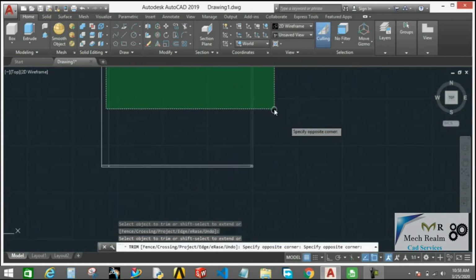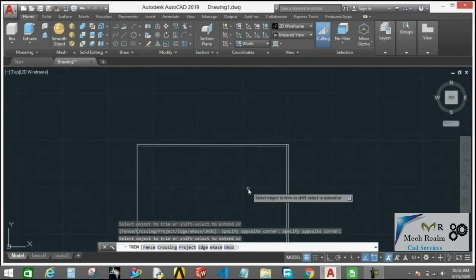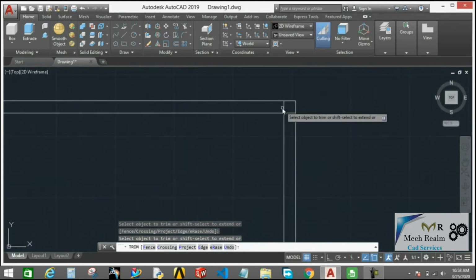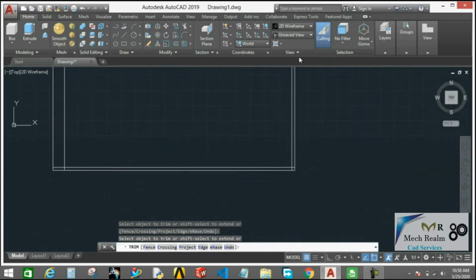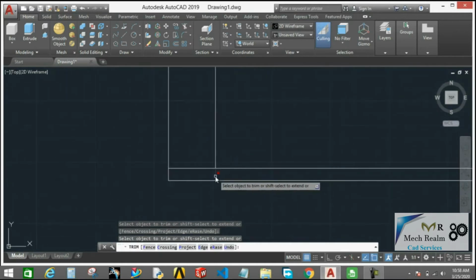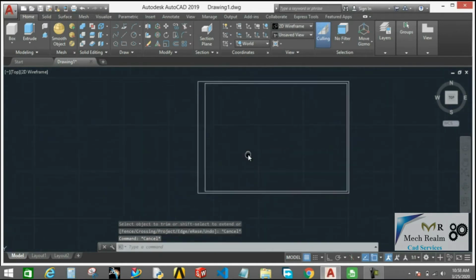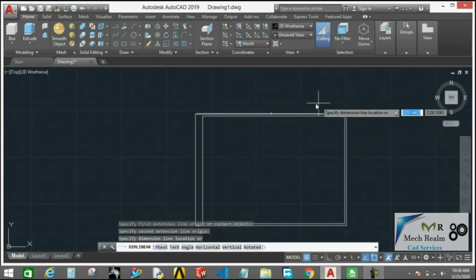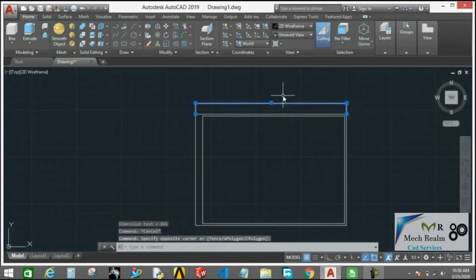Here also, sorry, let's control Z it, trim it, then towards this side, trim it to the bottom, and now to the left. Clear? Now if I verify the size, then this is of 841 mm.